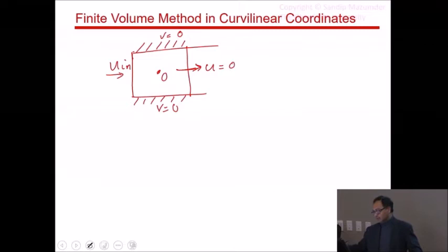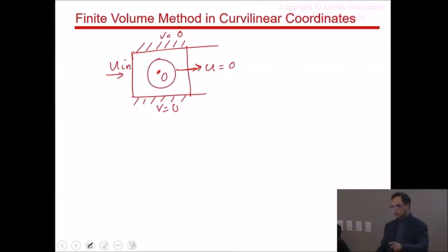And because of that mass imbalance, because the pressure here sees that there is a huge mass influx, it'll shoot up, so that the next iteration the pressure here is very high, the pressure here is low, and it drives out the flow. Okay? So right off the bat, you encounter a situation where things are perturbed heavily. You're starting with a huge mass imbalance, and that will often cause divergence.